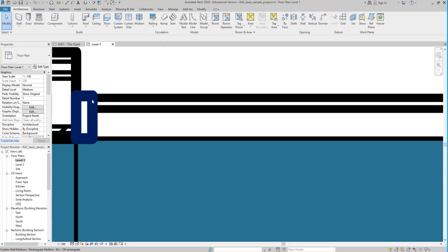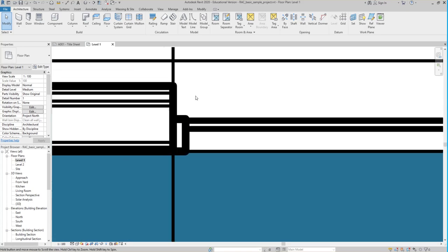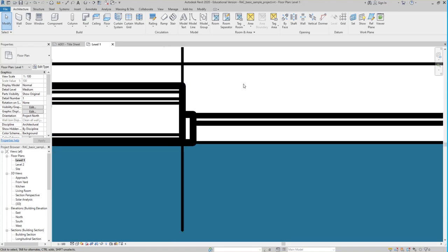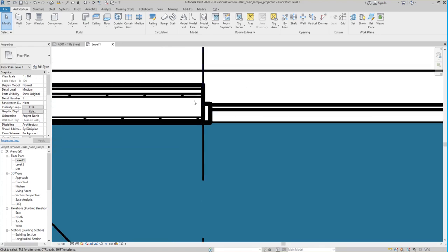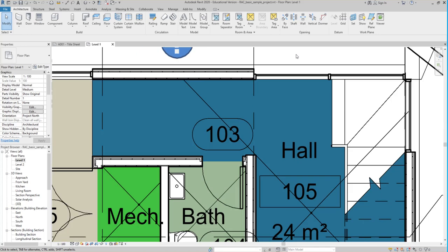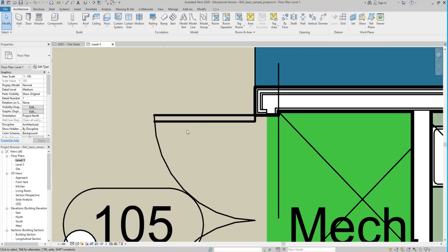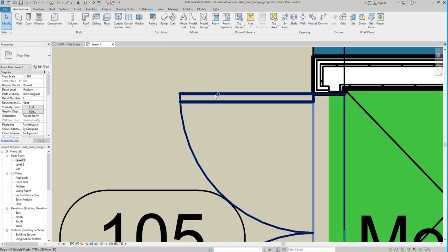And it looks like the windows are very similar. The lines with regard to the windows are very similar to the wall here, but I would bet that they're slightly thinner than the wall actually, okay? And then we have this thinner line weight down here that looks like kind of a windowsill or maybe a floor line or something, right? And then if we look over here at like the doors, we have the door panel, the wooden panel of the door, and that has kind of a medium pen weight, right? If the wall has a heavy pen weight, this is kind of a medium, and then this swing is illustrated with a light pen weight, okay?